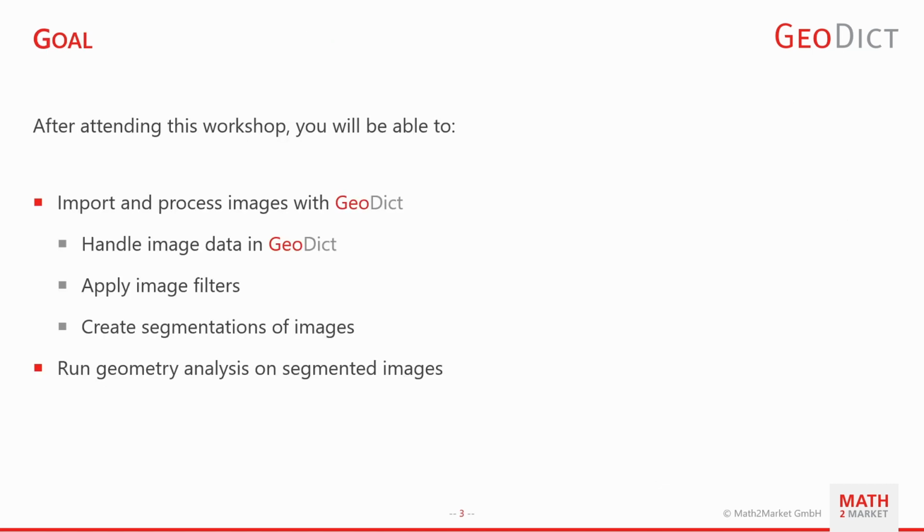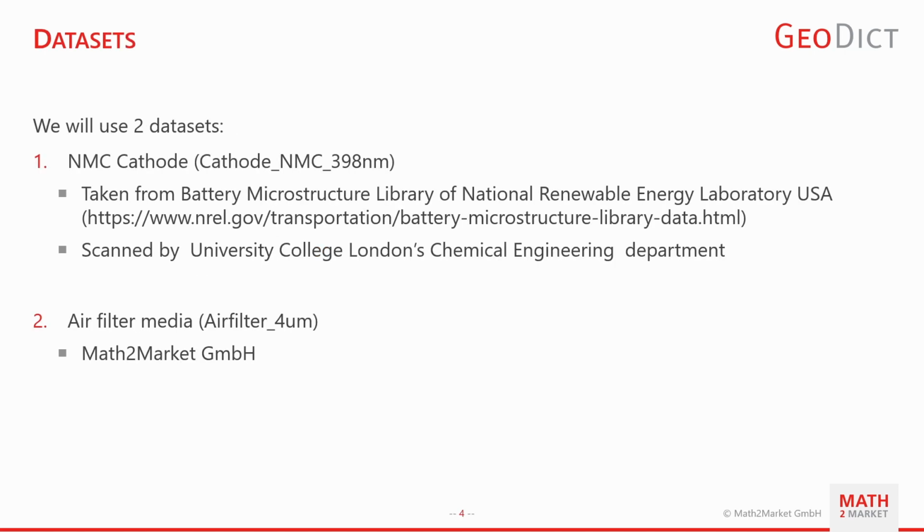In this workshop, we will tackle the topic of importing images into GeoDict and processing them, and also running some analysis on the segmented images. The goal at the end is that you know how to import image data in GeoDict, how to apply image filters and segment the images. Finally, you learn how to analyze the imported data, for example, how to obtain grain size distributions and grain diameter distributions.